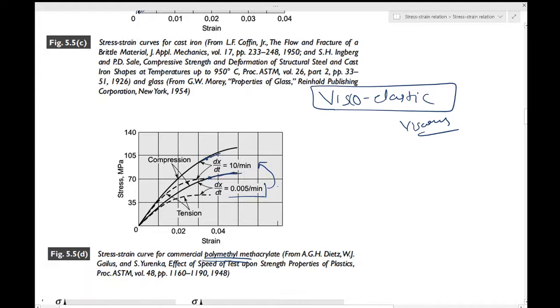At this time, you clearly know the difference between solids and fluids. A real solid is able to sustain a shear loading if you apply it, and an ideal fluid, which has no viscosity at all, will not be able to sustain a shear loading, meaning it will collapse. So that is where we end this discussion on the effects of strain rate.